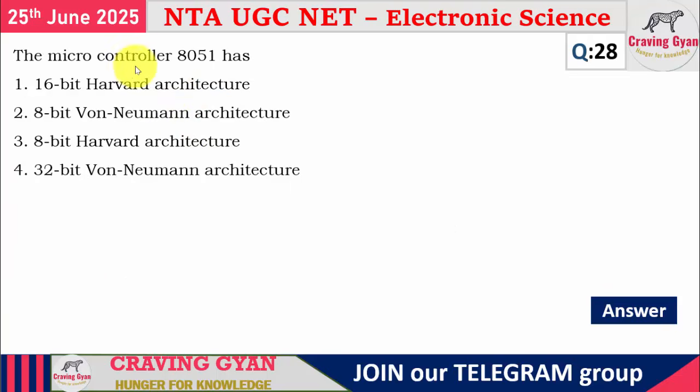28th question: the microcontroller 8051, what architecture has it adopted? It is 8-bit. Whether it follows Harvard architecture or von Neumann architecture. In the case of von Neumann architecture, both program and data are stored in a single memory. In the case of Harvard architecture, program and data are stored in different memories. In the case of Super Harvard architecture, especially used in DSP processors, your program will be stored in one memory, your filter coefficients in another memory, and your input sequence in a different memory.